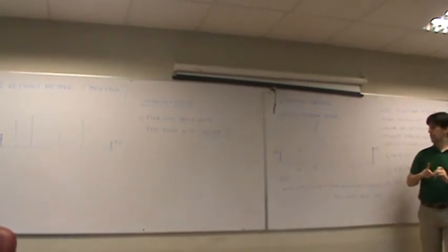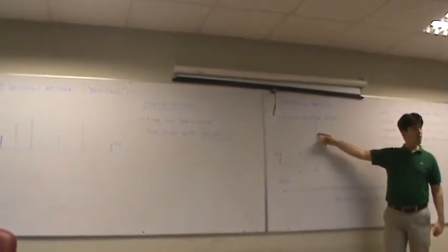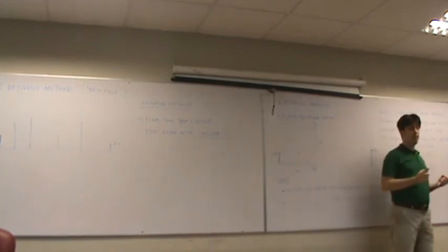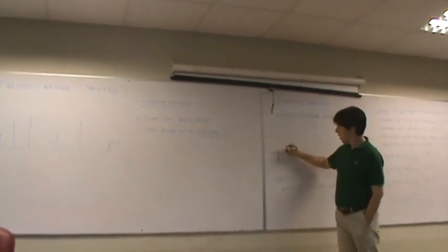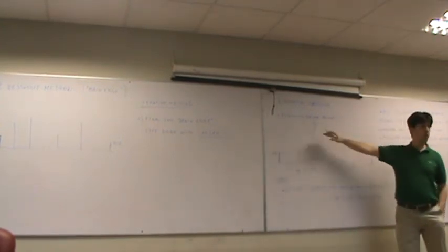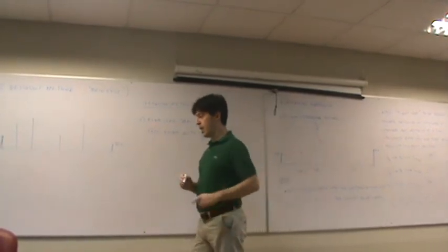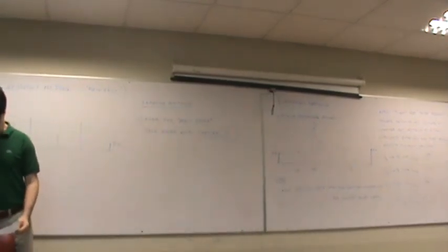So it is not obvious that the tallest obstacle has got the highest V, because you can have a very close by obstacle that is lower than this, but it's got a higher V. So you have to find the main edge. It's not the tallest one. That's why it's not trivial. So you identify the edge with the highest value.